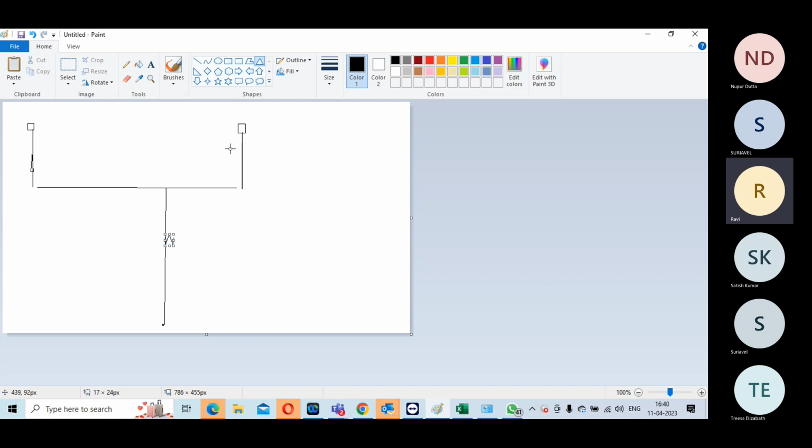For a setup violation, we can reduce the frequency and make it work. For hold, you can sell it to some customer who needs a lower frequency, right? Voltage is one option you can try and reduce, because you don't have to do anything with it. You supply a lesser voltage, that's all.